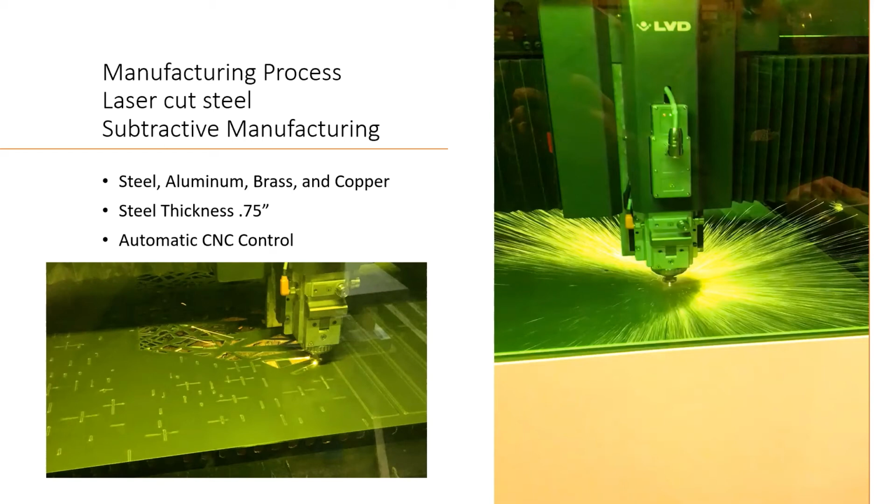is what is the gauge of metal that you're using? If you're using a relatively thin gauge in the site furnishings world, maybe 14 or 16 gauge, that's not going to provide you a lot of structural integrity. Now, if you're going down to maybe 11, 10, 9, 8 gauge metal, that's much, much thicker, and therefore it's going to provide more stability.